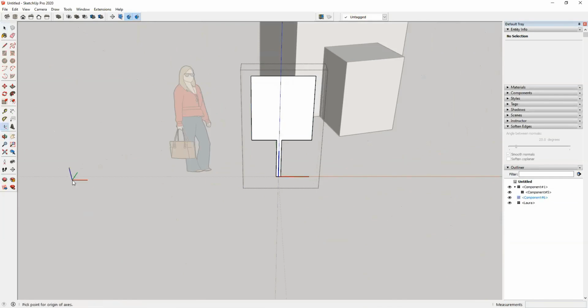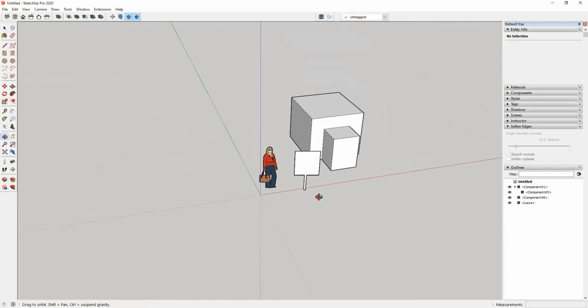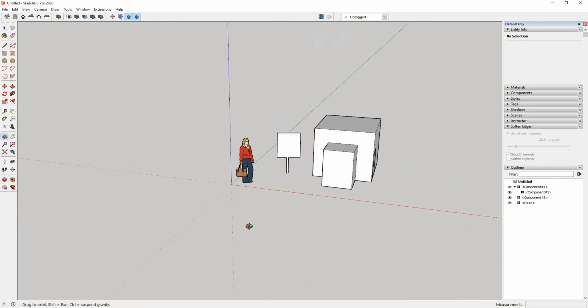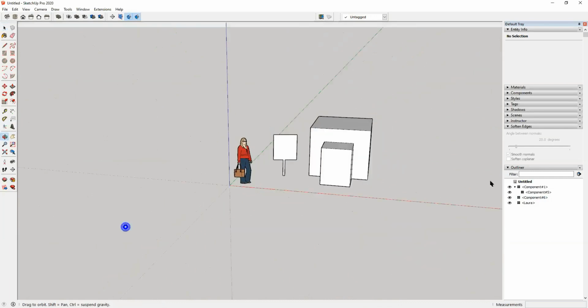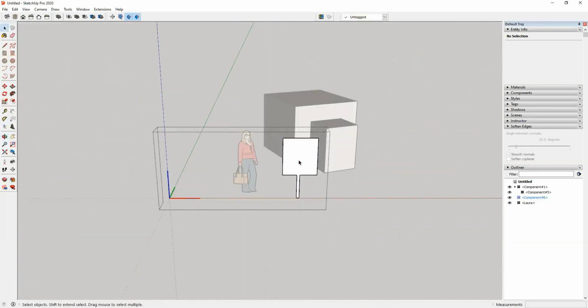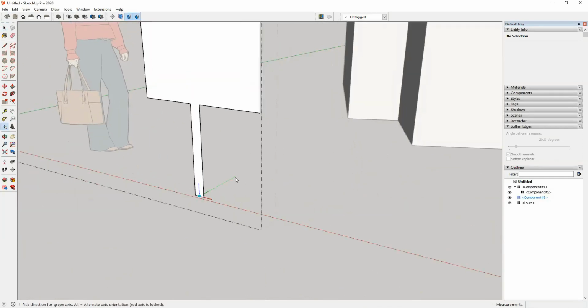Now in case I place it somewhere here, and close it, update it, save the axis, we'll notice that it will face the camera, but the center is now somewhere outside the object, right? So sometimes if you create the face me component, the axis might not be located where you want it to be. In that case, you need to update it properly.